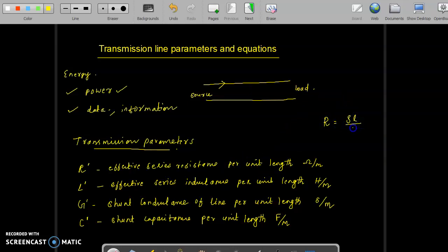So we can connect resistance and resistivity using these expressions. The resistivity depends on the type of material. All transmission networks possess some resistance. This resistance also depends on the length of the transmission line. So in today's derivation, we take Z as the direction along which the transmission line network progresses. So Z we consider as the length in this derivation. So the resistance R depends on the length.